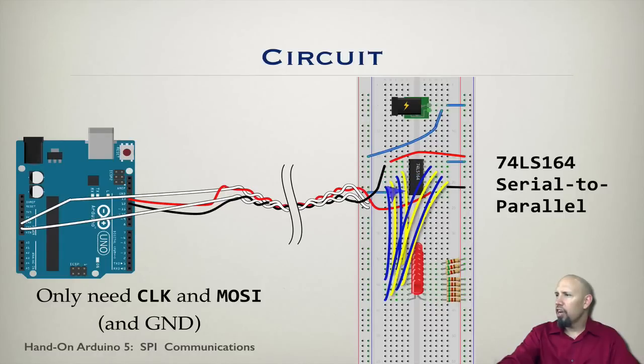The other 8 connections all connect to a bank of LEDs, and they basically go from 5 volts through these resistors, through the LEDs, and then they connect directly up to this chip. So basically what happens is when one of these channels goes low, it grounds one side of the LED and allows the current to flow.